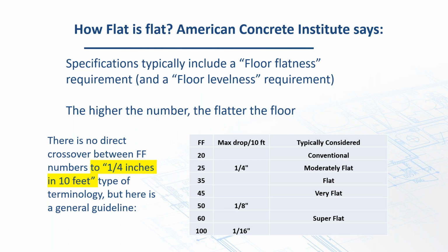There's a lot of differences between the concrete industry and how they get their flatness and what we need for the tile industry. So keep that in mind. They're measuring the slab within 72 hours. We're coming back on the job anywhere from 4 weeks later to beyond that, and now we're going to set tile. Do you think that slab's exactly the same as it was the first 72 hours? No, the odds are slim.